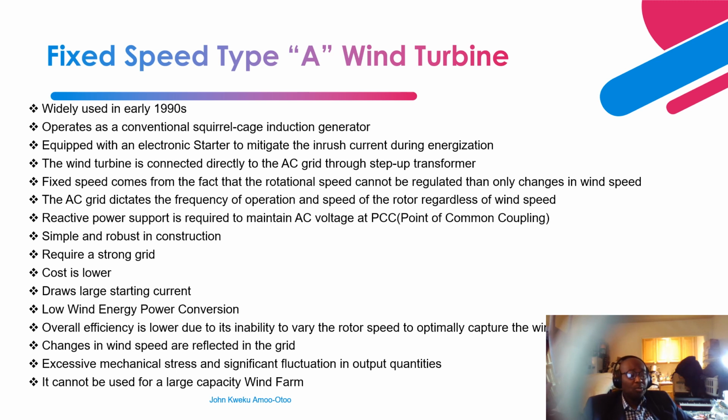It is very simple and very robust in construction. It requires a strong grid, or a stiff grid. And when we say a strong or stiff grid, what does it mean? It is a grid that has a high amount of short circuit current capability.